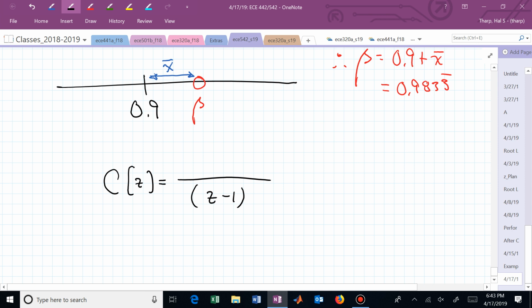Whew. So what's my PI controller? I'll do the hard part. You know that's there. You've just found where your 0 is. What's left? Figuring out k. And what do we do to get k? We crank up k until we get those triangles to actually be on top of the triangles that we want, which is at 0.9 plus j 0.1.